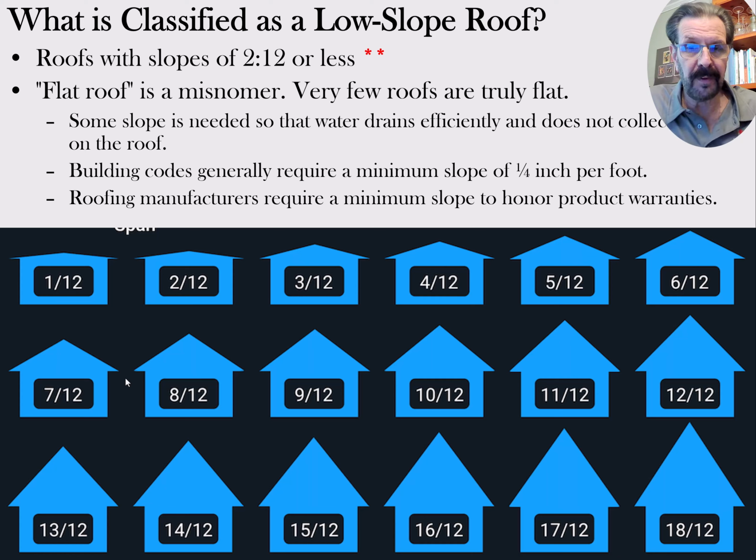So be very careful when somebody starts talking about the pitch of a roof, because it's a meaningless number by itself, unless you define those numbers and those terms. Many people, and even textbooks, get it wrong, so just be very careful. Roof slope is a much more reliable definition to deal with, and it has real mathematical value.